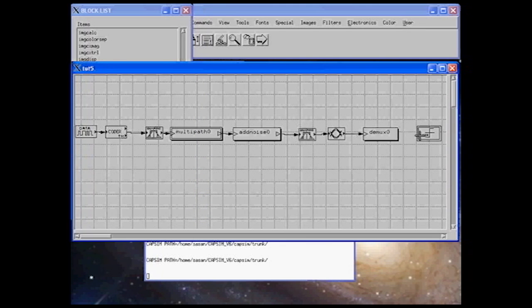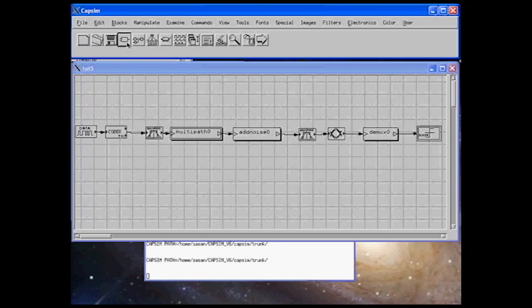The slice block is actually going to take the samples of the match filter and then perform a decision on them. In our case, the decision being, because we are sending bipolar, whether it's greater or less than 0. So the slicer is actually between plus and minus 1. Let's go ahead and connect these two up. Let's also save the topology.